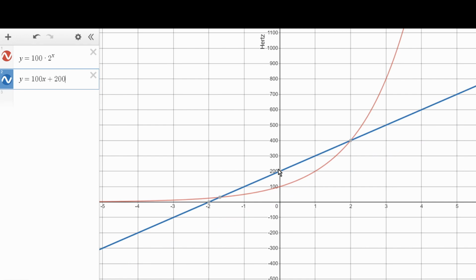I've added 200 hertz of bias. So now at 0 volts on the linear modulation, we're still running, and we have to go down to -2 before we'll go through 0. This represents 100% of the range. So 200 hertz is 100% of the range, and if we go up to +2, we're at 400. So this is plus 100% and minus 100% before we get to 0, before it starts reflecting and going into negative frequencies. So if we modulate with plus and minus 2 volts, you can see that we never go through 0 from here to here.